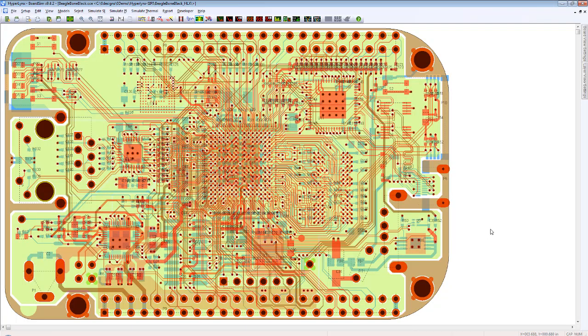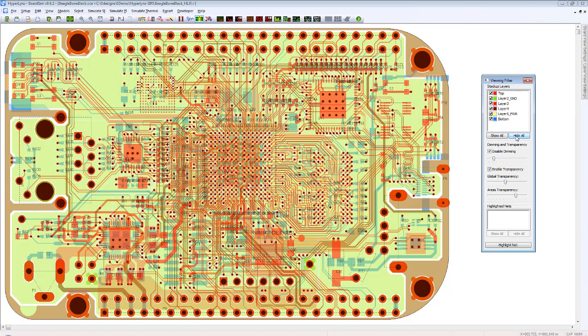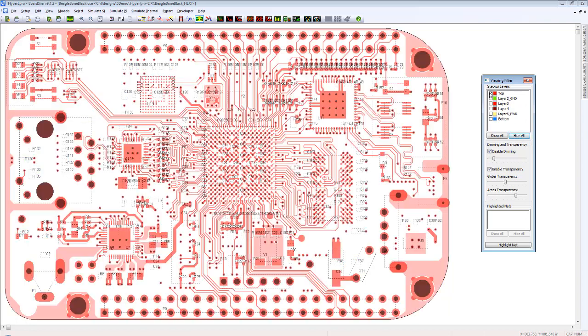Here we see the PCB layout opened in a signal integrity analysis tool. To review a little bit how the routing was done, we see it's a 6-layer board. In this area we see the Texas Instruments Sitara processor, and in this area the DDR3 low power memory. In my project I used Micron devices, and I also downloaded the IBIS simulation models of the two parts from the websites of the component makers.